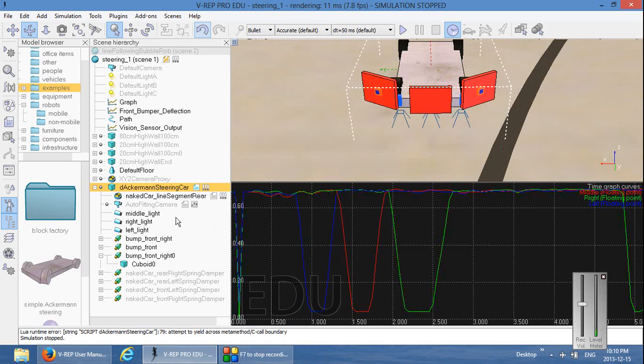You can also play around with moving them closer together. What this will do, it will allow you to get the line, rather than from a discrete state of being either middle, left, or right, to more along where you can say it's either here, here, or anywhere within this area. This should allow you to get a lot better control and should help you design your robot better. I can't really tell you exactly how to do that, but you could try setting up experiments where you move the line relative to your vision sensors and see just how much overlap you get.